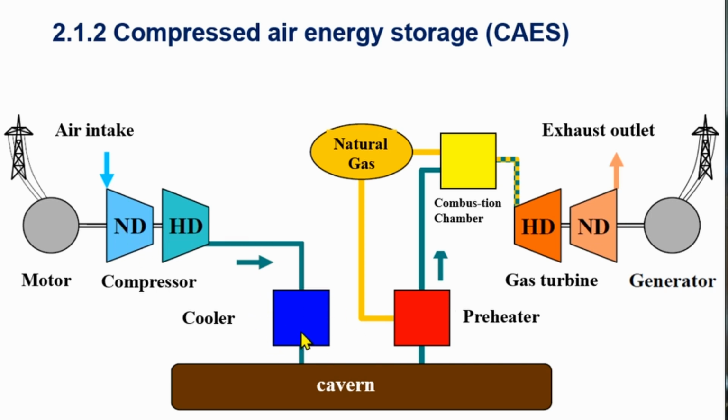During the compression process, there is a release of heat. If you pump up your bicycle with an air pump, you feel it, it gets hot. And you can use that heat for the preheater, for example. So this means adiabatic use. This improves the efficiency, which is usually quite poor for such a CAES system. And here you have the storage, the cavern, and this could be really high and therefore provide power for a long time, even if the air density is relatively low.